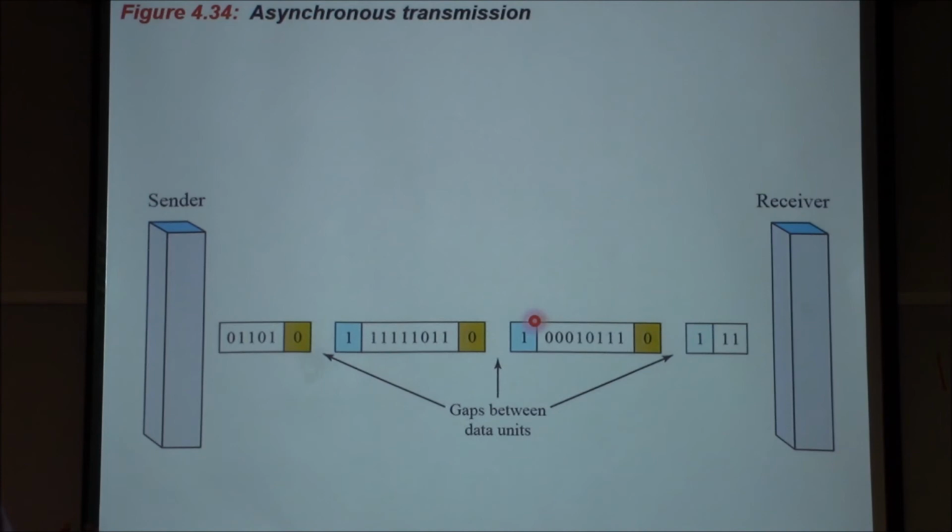So we will send the data one byte at a time. That is the asynchronous transmission, 1 byte at a time. It's always 8 bits of data, so totally 10 bits. Yes, we will use 1 byte at a time, so that means 8 bits at a time. We will add 1 or more bits as a guard to identify the starting and the ending of the 8 bits.